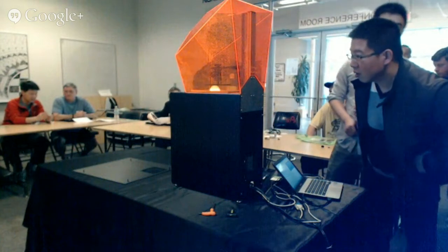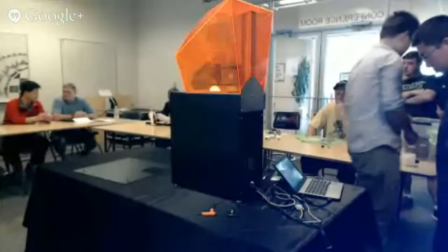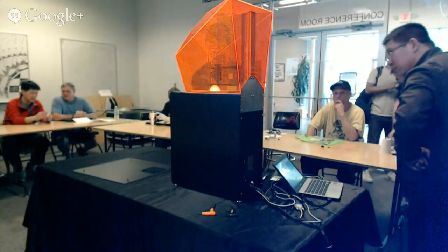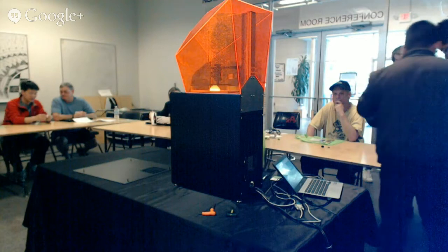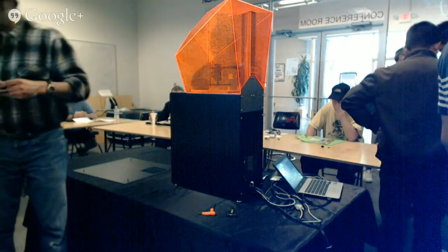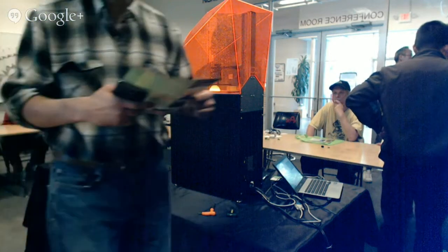Normally, on a silicone bed, you would always print this at some angle so that this wall gets spread out along the surface. So you don't get a single area getting all of the cure all at once. Spread it out. And that makes silicone last longer. With our Teflon films, we don't worry about this. It doesn't make any difference.